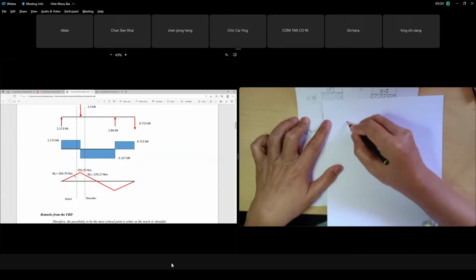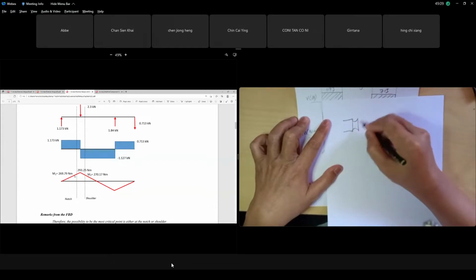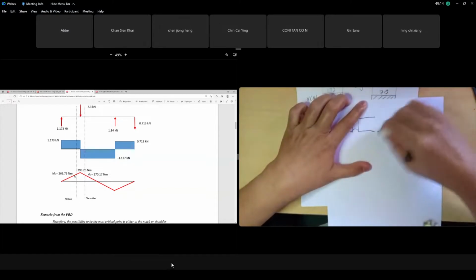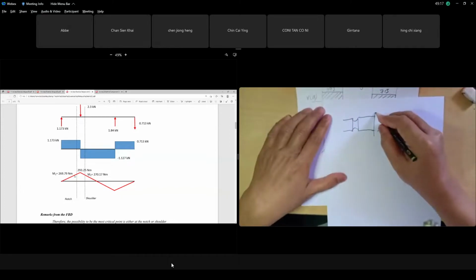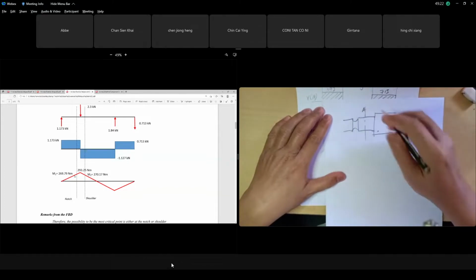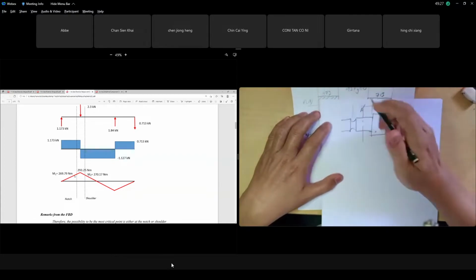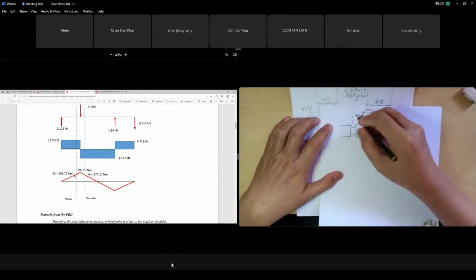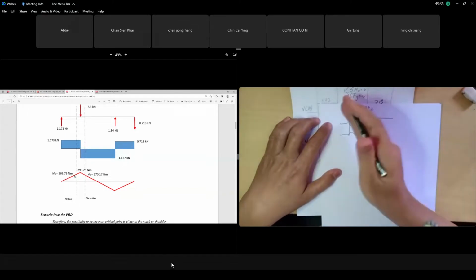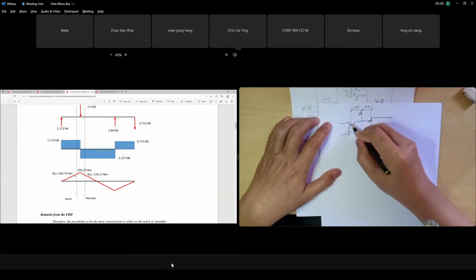that's why I said earlier, you have the situation of your groove. This is your groove, and this is your shoulder. You don't have to draw like that, it's just to explain to you. Earlier we have our point A here. This is our point A. So we know that the offset distance everything here is 20 mm, 20 mm to the right, 20 mm to your left, 20 mm from your point A for your groove. This one is for your shoulder. At the shoulder we have a fillet radius. We have a fillet here at the shoulder, and this one we also have a radius.